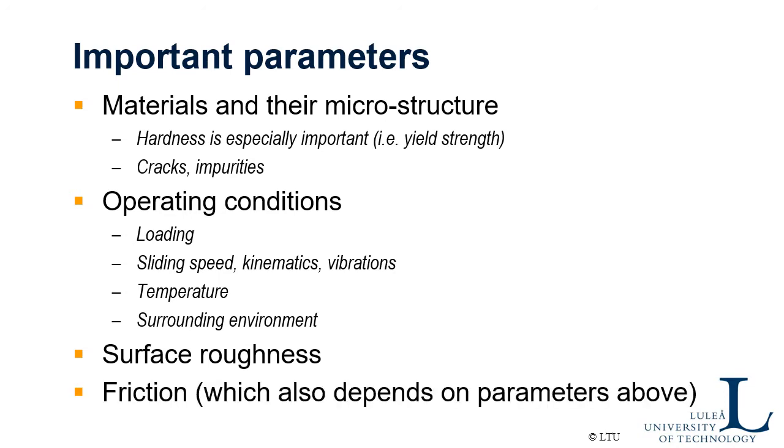And finally, I also want to bring up friction. Even if it's a little bit, friction is an effect of the parameters I mentioned here already, but friction itself will also influence the wear rate. The higher the friction is, the higher the stresses on the surfaces will be, so most likely the wear rate will also be higher when friction increases.